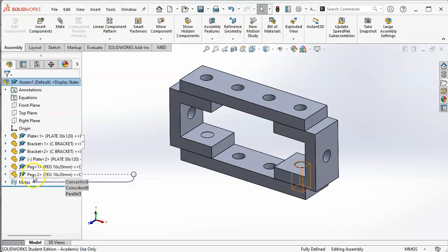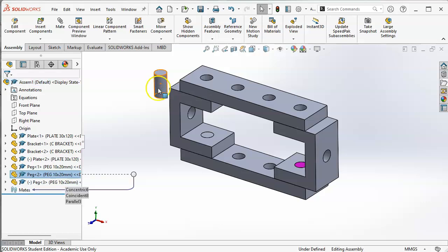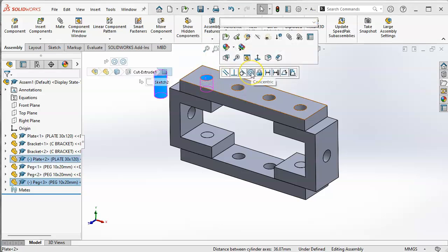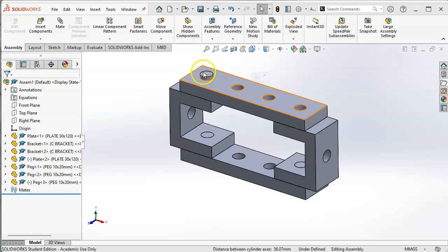We have one more. So Control left button, drag into the work area, let go of the left button, let go of the Control key. There's a lot going on there when I say it like that, but really once you have the muscle memory in your fingers, they just take off and do whatever they're doing with the software. So concentric, and oh, it stayed up there just long enough that I didn't lose it. So lock rotation. If I missed it, not a big deal.